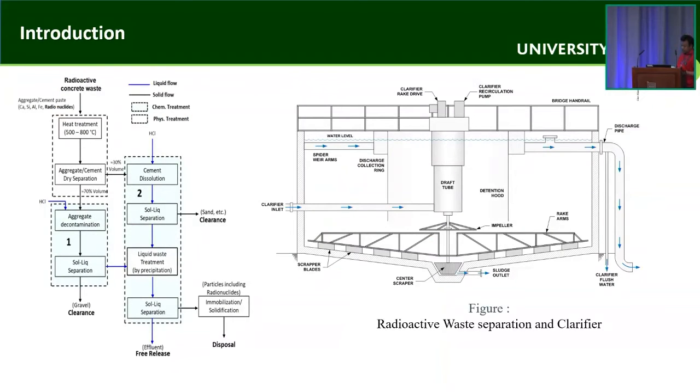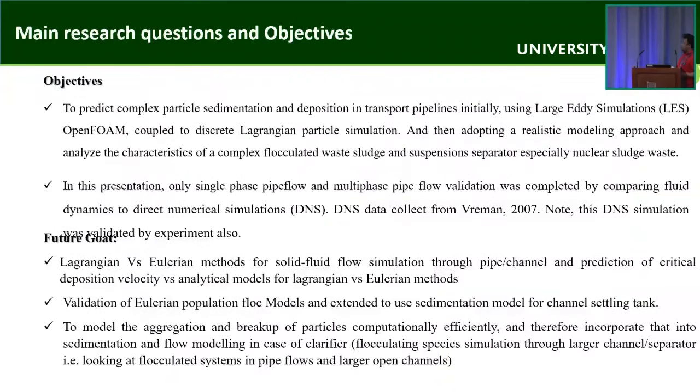However, CFD methods do not adequately capture the physics of complex and shear-dependent flocculated particle phases with respect to the flow field and the fluid condition. Hence, my main primary goal, as I told already, is the prediction of complex particle sedimentation and deposition in transport pipelines, initially using large eddy simulation coupled to discrete Lagrangian particle simulation, and then adopting a realistic modeling approach and analyzing the characteristics of complex flocculated waste sludge suspension, especially nuclear sludge waste.